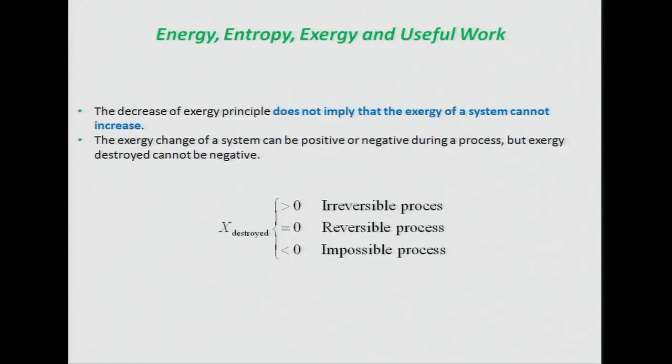Okay. Same rules, right? The decrease of exergy doesn't mean to say that a system cannot increase its exergy. It just says an isolated one can. The exergy change of a system can be positive or negative during a process, but the exergy destroyed cannot be negative. In other words, I can't just get that exergy back. It's like entropy generated. It's an irreversible process. So if there's no exergy destroyed, it's reversible, which we've discussed. And if it's less than 0, it's impossible. But those you can tell by looking at entropy.